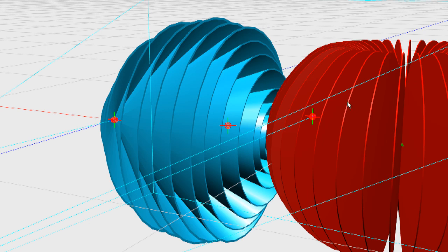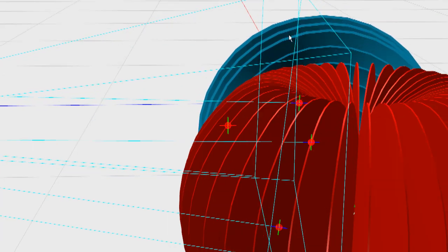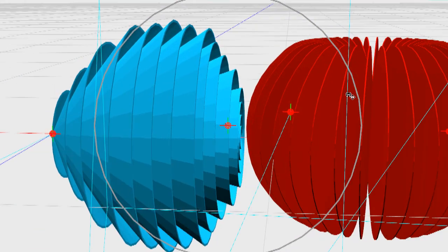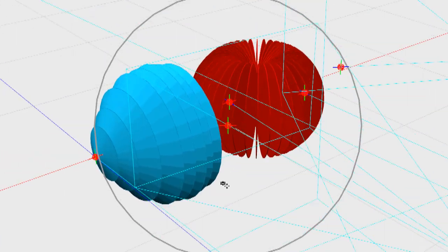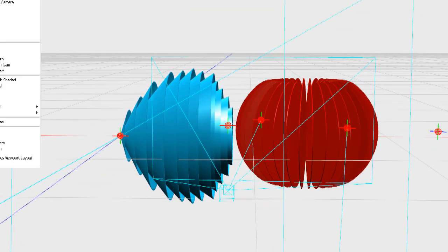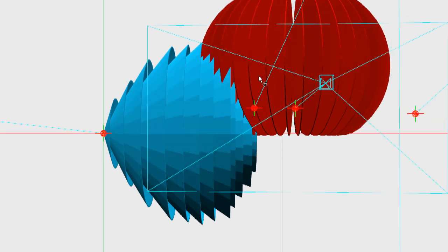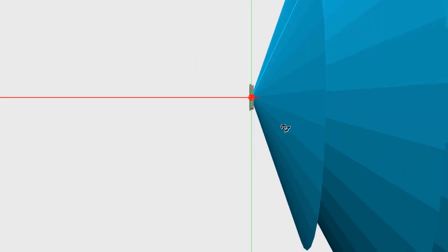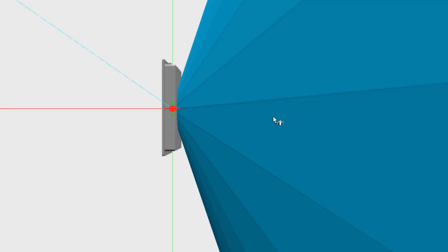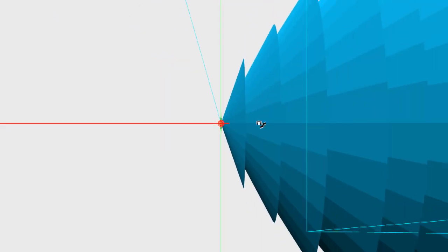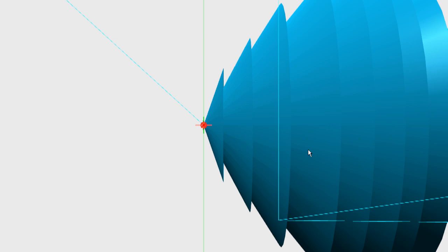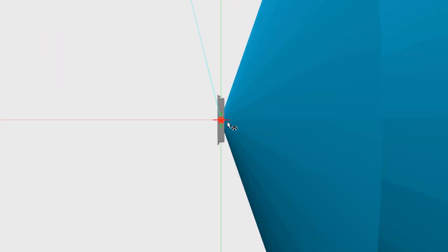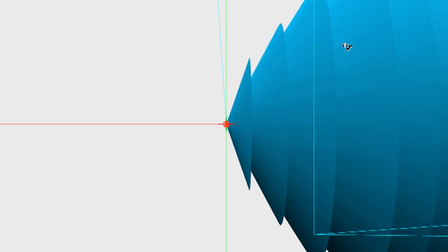This here is almost a horizontal cross section. Now it's not perfect, so again we've got that loss, but the great thing about the circularly polarized one is that it's very consistent. And assuming you're keeping yourself within the range, you're going to have a very good signal. And again, remember we're on a patch antenna here, yeah. Because it's 8 decibel, it's not omni, yeah. So we have to make sure that we're pointing the 8 decibel circular antenna at the aircraft.